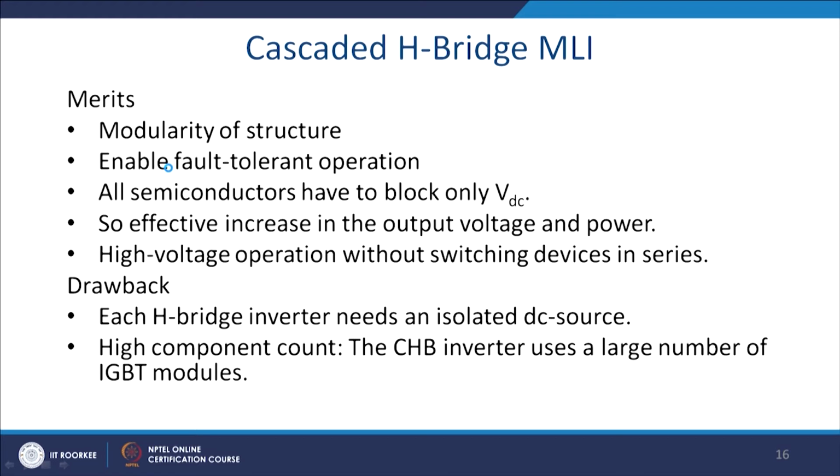So, what is the advantage of it? The advantage is its modular structure. You just put them like bricks and build the house. It enables fault tolerant operation, because redundancy is more, as different voltage levels can be generated with a few more combinations.